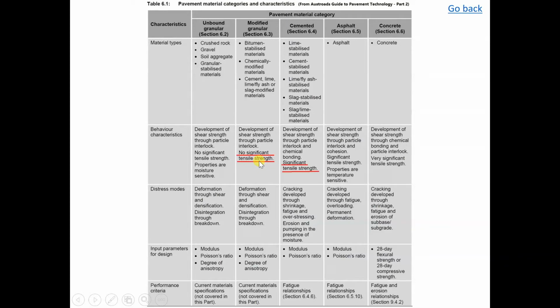So that means the development of shear strength is through particle interlock. Mostly it is through shear, which means the failure is deformation through shear and densification.